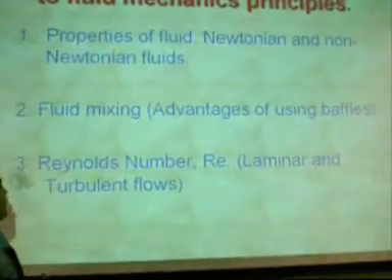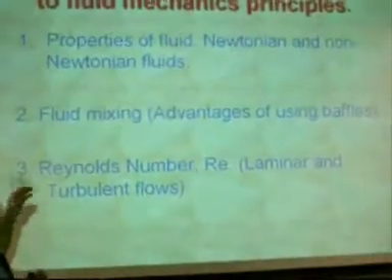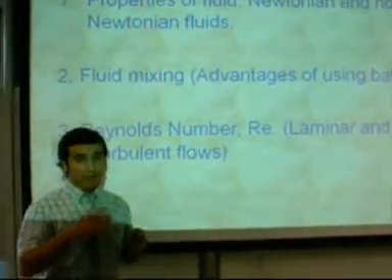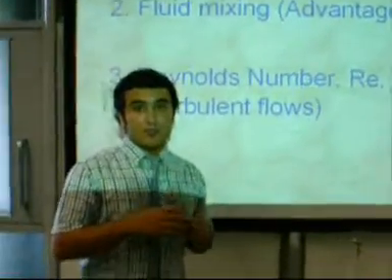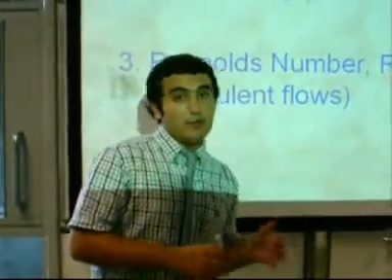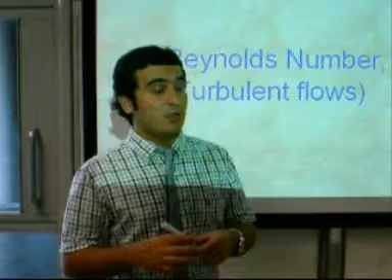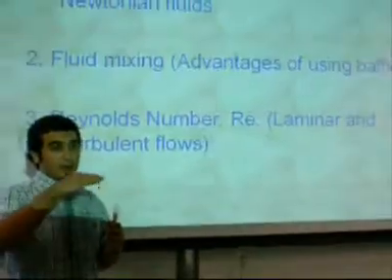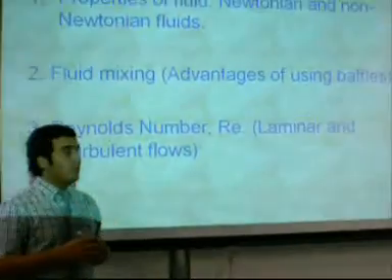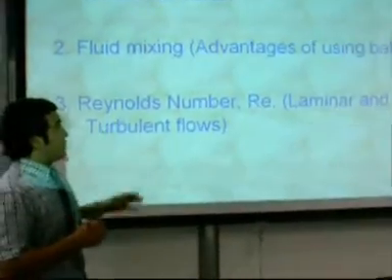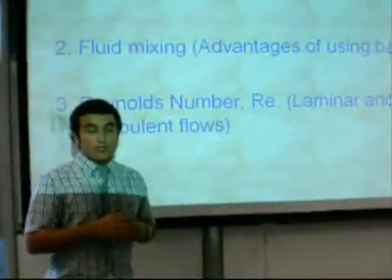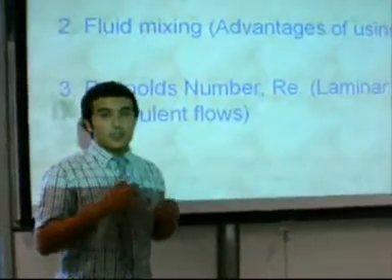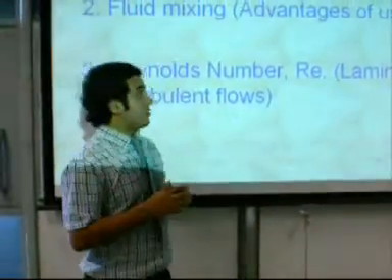The second link I found was fluid mixing. Last time we had an experiment on fluid mixing, where we used baffles. We saw the difference of mixing with a baffle and without a baffle. In this OBTA, we have two baffles installed in the tube, and there are very good advantages of using these baffles. They increase the intensity of mixing.